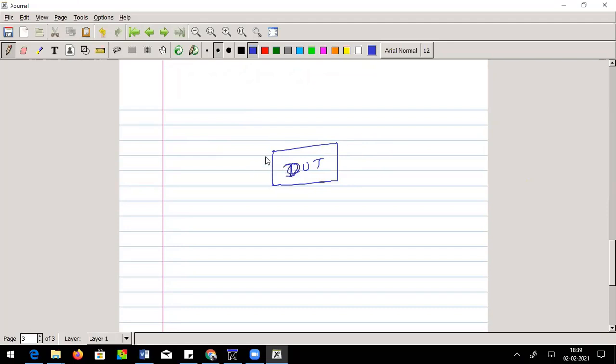So after finishing, suppose you made a half adder, A, B, sum and carry. Now I want to test this. What is the usual way which we are trying to do? I am forcibly giving some value of A and B and checking whether sum is equal to so and so, carry is equal to so and so. But the reality is, I am not verifying all possible combinations of my input. So starting from 0, 0, 0, 1, 1, 0, or for multiple combinations, I'm not trying it.